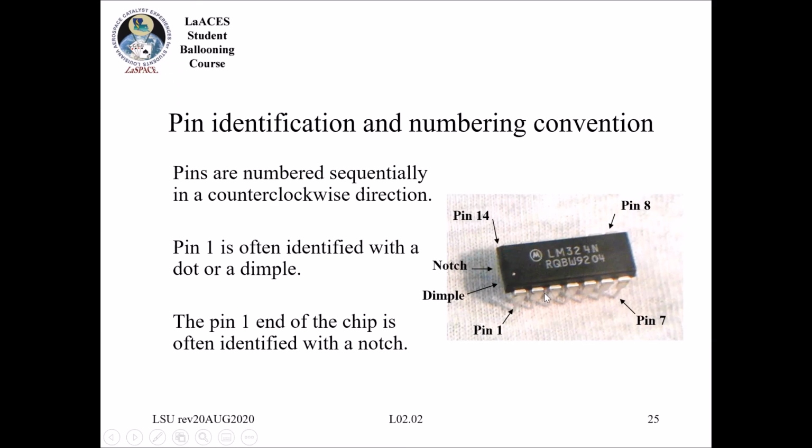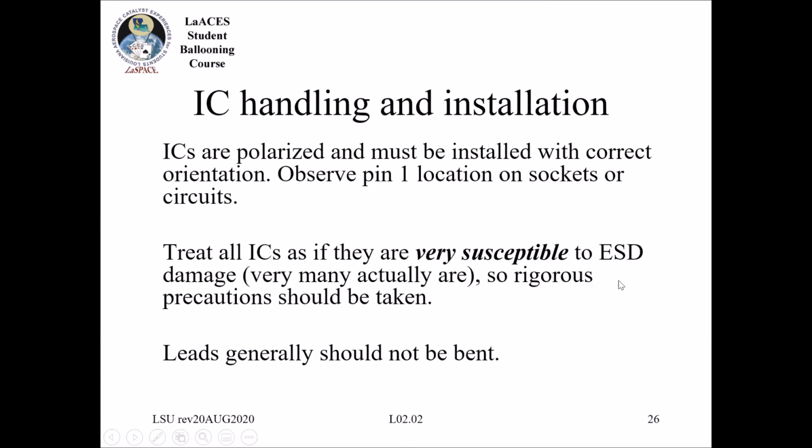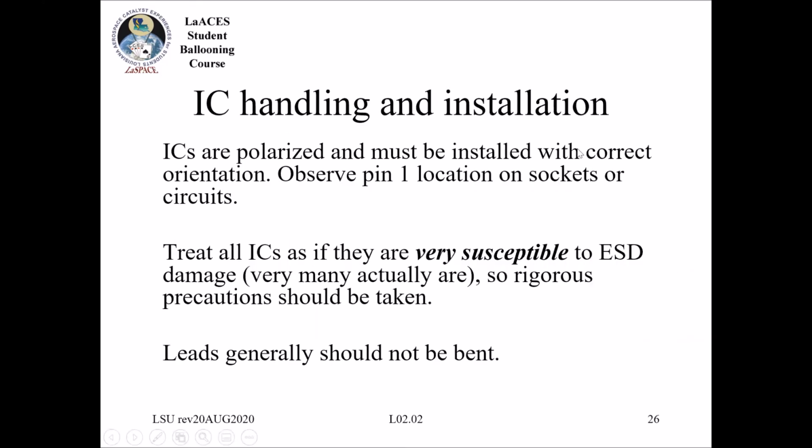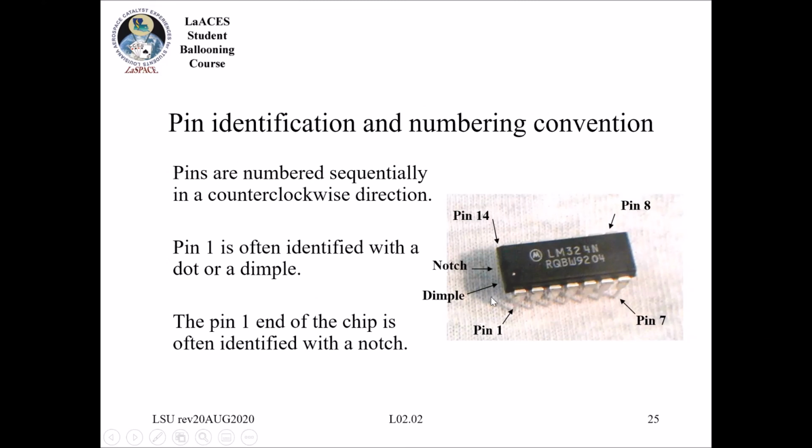So it goes pin 1, 2, 3, 4, 5, 6, oops, sorry, 7, and then it goes across 8, 9, 10 through 14. So every time on an integrated circuit, or on a connector as well, these pin orientations matter, and you need to study them and understand them. Just to note, this is the typical configuration for this type of integrated circuit, where you start with pin 1, it goes to pin 7, then it goes across to pin 8, and then to pin 14.